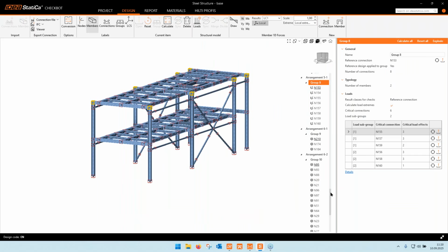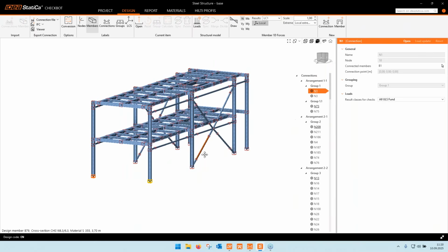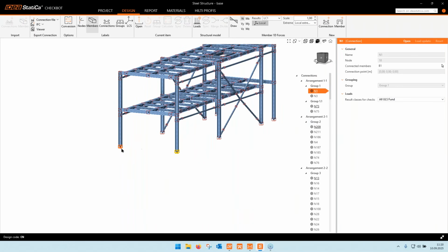One more important thing before we proceed is why I mentioned that article about what's happening behind the scenes: I do not recommend using this option for footings. Why? Because with footings, as you've seen, what we are taking into account are the load effects. What we are not taking into account, and what might be governing for footings, are the edge distances, like concrete edge breakout, which might be the governing failure mode.